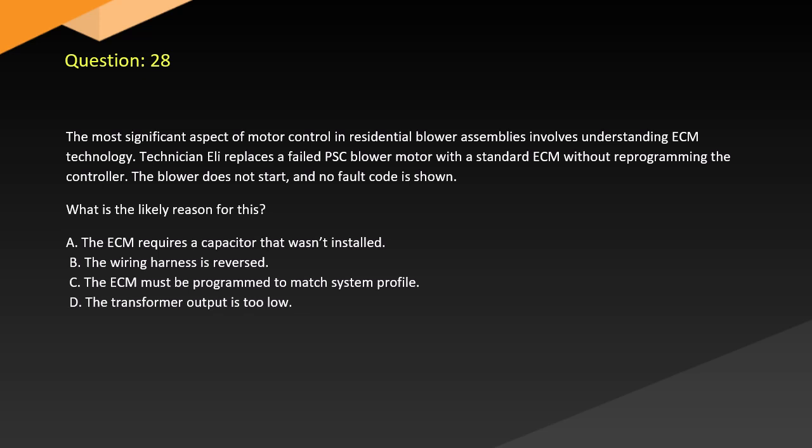Question 28. The most significant aspect of motor control in residential blower assemblies involves understanding ECM technology. Technician Ellie replaces a failed PSC blower motor with a standard ECM without reprogramming the controller. The blower does not start and no fault code is shown. What is the likely reason for this? A. The ECM requires a capacitor that wasn't installed. B. The wiring harness is reversed. C. The ECM must be programmed to match system profile. D. The transformer output is too low.